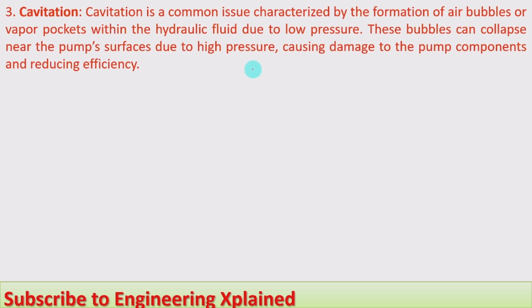When at low pressure these bubbles are formed, and whenever they go to the pump, there the higher pressure will be present. There they will collapse, causing damage to the pump components and reducing the efficiency.